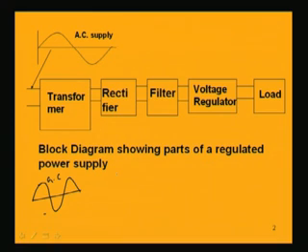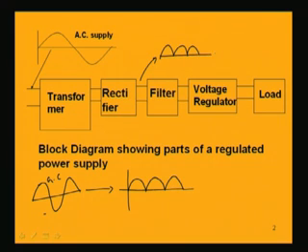So, if I use a full wave rectifier, after the transformer steps down this input voltage to its bearable level, it will be rectified. If I use a full wave rectifier, I will be getting this type of output voltage which is rectified in both the halves. So, after this rectifier, here we will be getting this type of pulsating DC voltage. This is called pulsating DC because it is not purely DC, but we have to get a DC which is constant voltage from this pulsating DC.